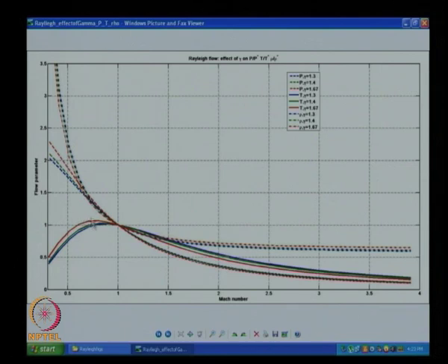And beyond a point, they all look the same and the temperature seems to flatten out at that point. Temperature need not change, pressure is same as density slope there. After some point, it will just change the other way. Everything will go the way we expect things to go. Temperature should drop when Mach number increases. That is happening around this region. That is what you are seeing in here.